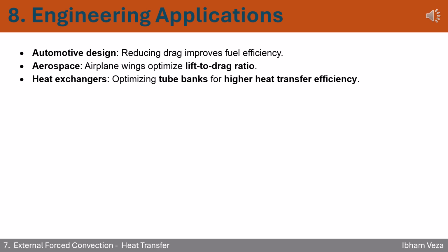In automotive design, reducing drag isn't just for speed, it's for saving fuel. The less resistance a car faces, the less energy it needs to move, making it more fuel efficient. In aerospace, the focus shifts slightly. It's not just about cutting drag, but improving the lift-to-drag ratio. That means getting the most lift for the least amount of drag, which is essential for efficient flight.